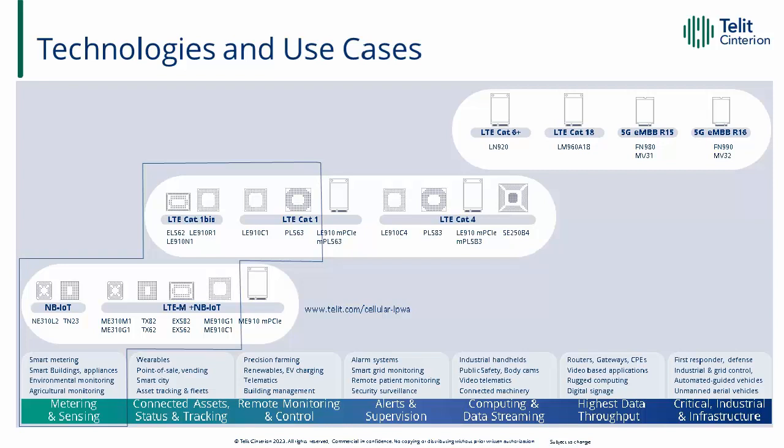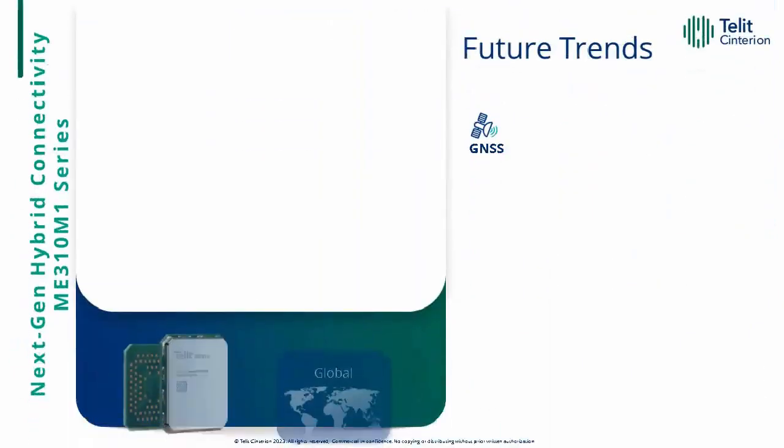And then the row above, the middle row, with Cat1, there are multiple devices with footprint compatibility, and these tend to follow either global or regional SKUs, which you don't need in the MTC devices. And then we have Cat1 BIS, which is a simplified Cat1 device. And probably the key difference here is only one antenna supported, so there's no RX diversity required.